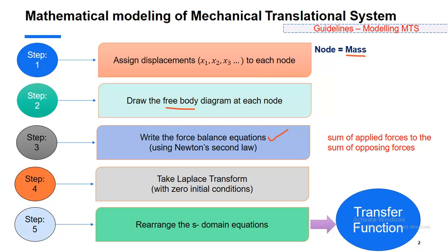Then we have to take a Laplace transform of those differential equations formed by the force balance equation. And we have to rearrange the Laplace domain equations. Finally, we will get the transfer function.